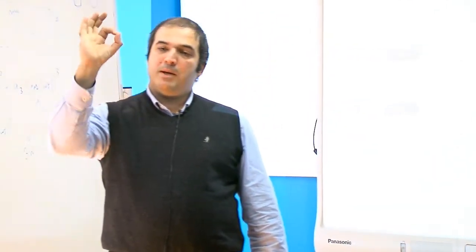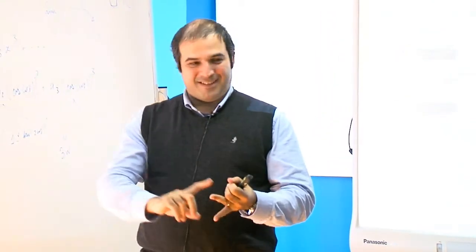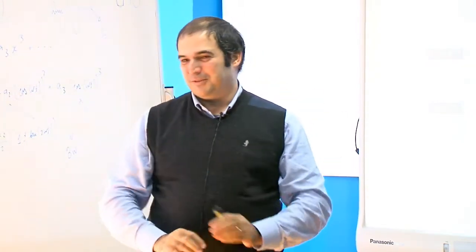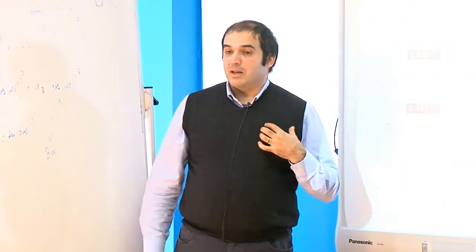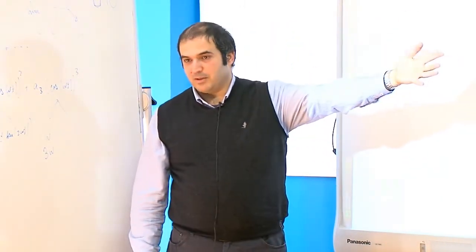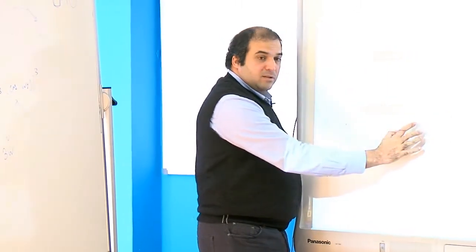So what we do with this, first, this is used to kill the harmonics of these generators. Because this is another important problem. When you go to Microwave Office, when you go to ADS, you pick up a generator and you have a perfect generator. It doesn't have phase noise, it doesn't have harmonics, everything is good. It has a 50 ohm load, everything is good. You go to the lab and you have harmonics, you have phase noise, you have all this. And the problem is that it can mask your device. So you think you are measuring your device, and no, you are measuring the instrumentation in the lab. So it is important to know that these filters kill the harmonics.